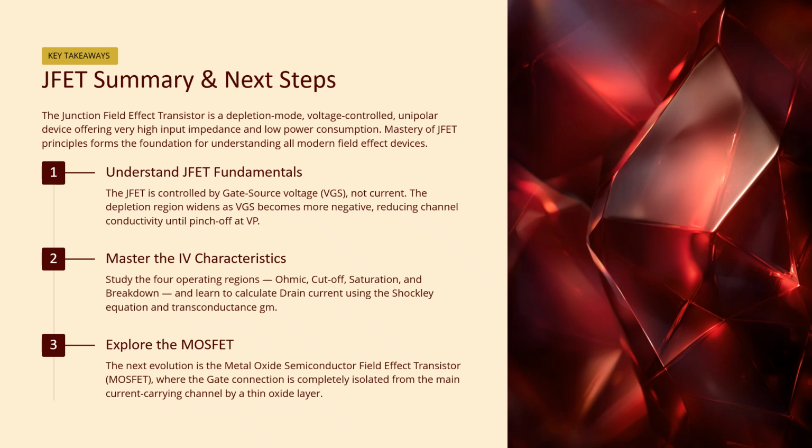Master the 4 characteristics. Study the 4 operating regions, ohmic, cutoff, saturation, and breakdown, and learn to calculate drain current using the Shockley equation and transconductance GM. Explore the MOSFET. The next evolution is the metal oxide semiconductor field effect transistor, MOSFET. Where the gate connection is completely isolated from the main current carrying channel by a thin oxide layer.